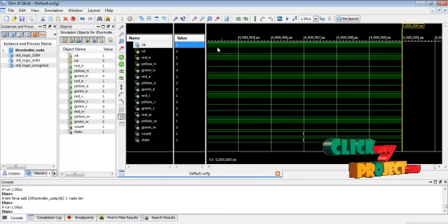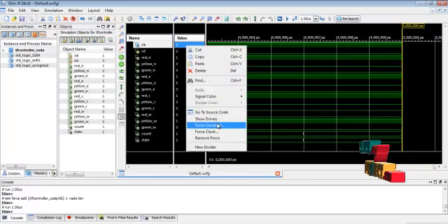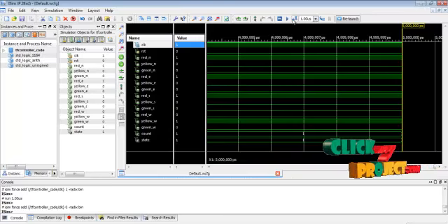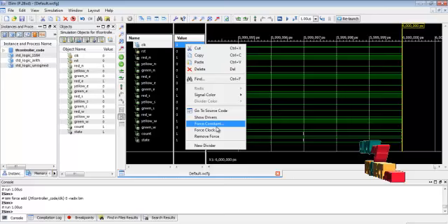Then the position changes for red, green and yellow for the overall 4-way traffic light controller architecture. Then we apply the clocking, count the counting result, and change the required state position according to our counting result.